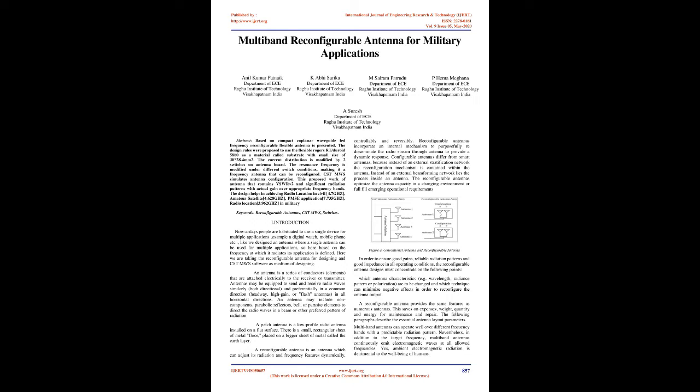with a small size of 30*28.4 mm². The current distribution is modified by two switches on the antenna board. The resonance frequency is modified under different switch conditions, making it a frequency reconfigurable antenna. CST MWS simulates the antenna configuration.